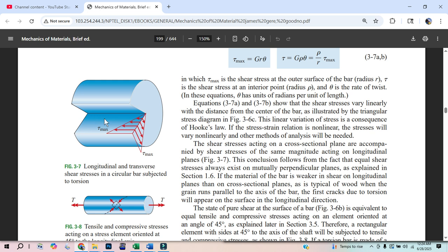So these 2 numbers by Hooke's law, the stress is related to that angle. And when this number is maxed for the material, that angle is max, and that's always a good, useful place to start. This angle could be an angle of 0.004. It's a small angle, but if this shaft is long, like even just a meter long, that's 1,000 millimeters times 0.004, the arc length of 4 millimeters. So this thing will rotate